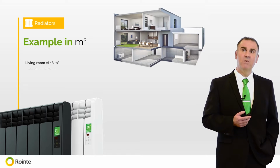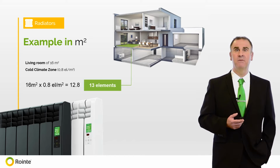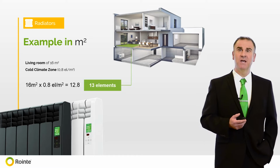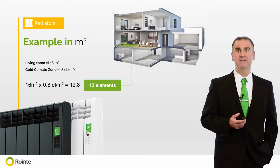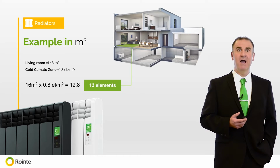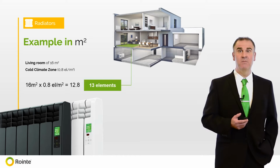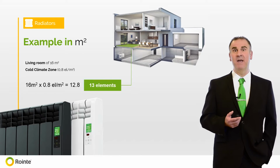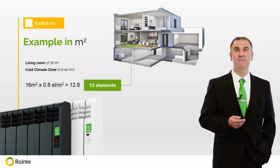In this example, we have taken a room of 16 meters squared in the cold climate zone. The calculation is 16 meters squared multiplied by 0.8 elements, which equals 12.8. Therefore, a minimum of 12.8 elements are required to heat this room. This would ideally be one Rointe 13-element radiator.